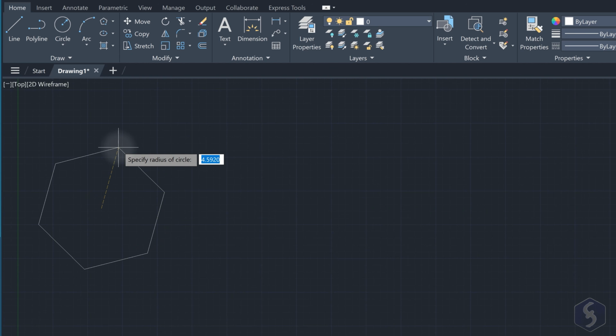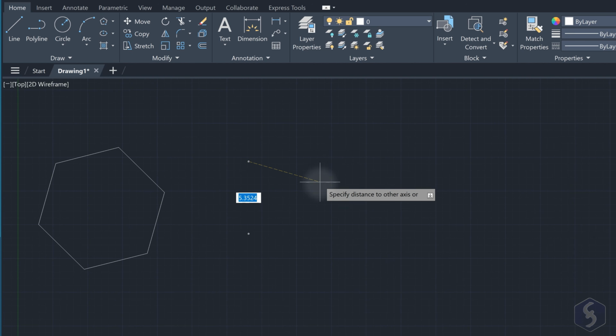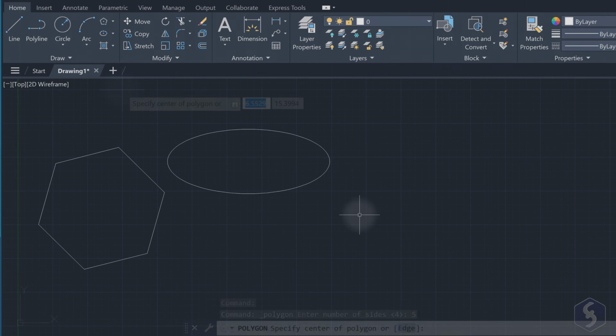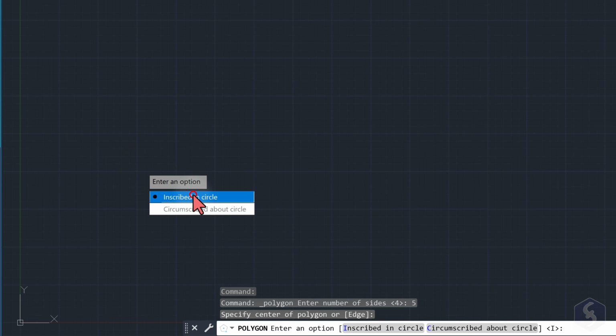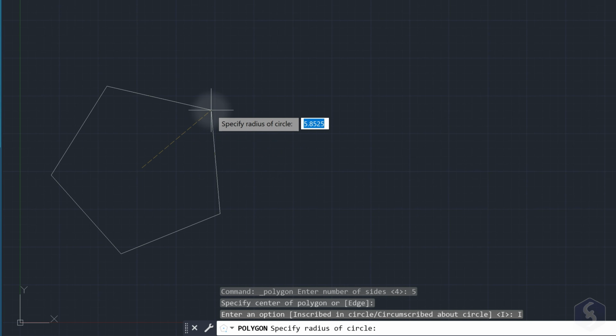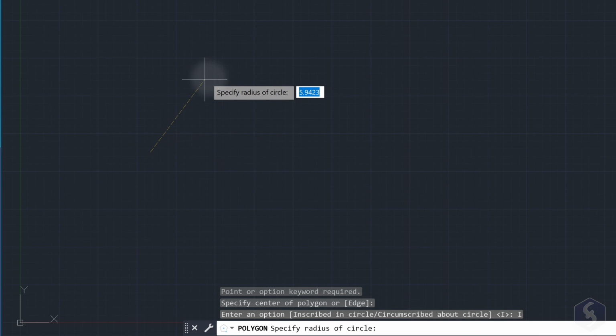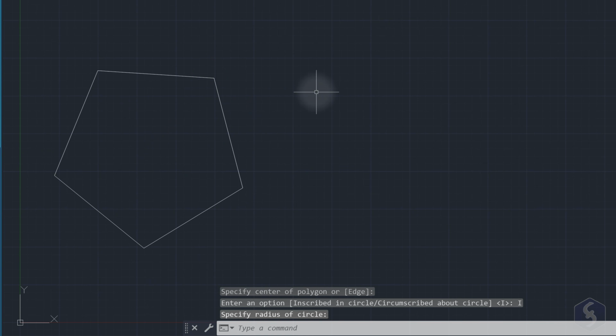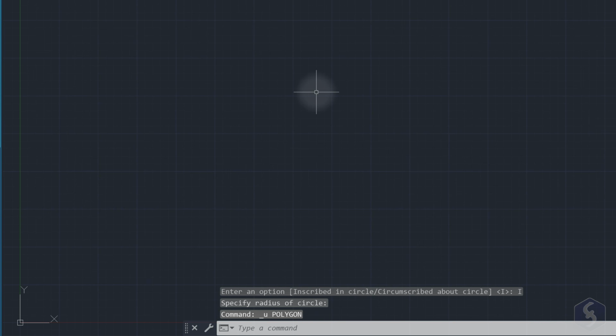Then fix 2 points. To draw an ellipse, enable the Ellipse tool and fix 3 points. AutoCAD shows a live preview of the object in progress. Undo the drawing with the Escape key, or use Ctrl or Command and Z to undo any shape applied.